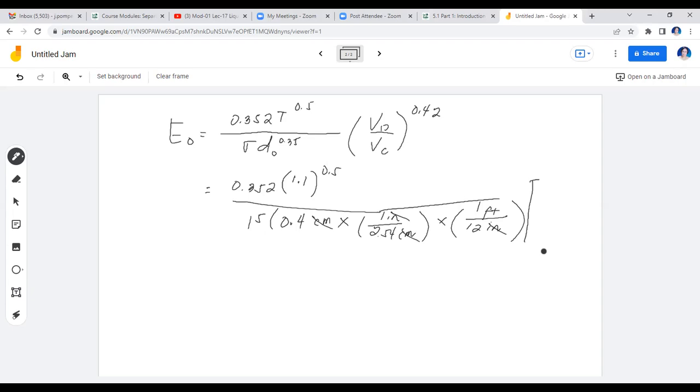Then we have the V sub D. So your V sub D is the flow rate of the continuous phase. What's your flow rate for the continuous phase? 400, miss. 400. And what about for the dispersed phase? 600, miss. 600. And you raise this to 0.40. And that's it. This is how you determine the tray efficiency for the perforated tray tower.